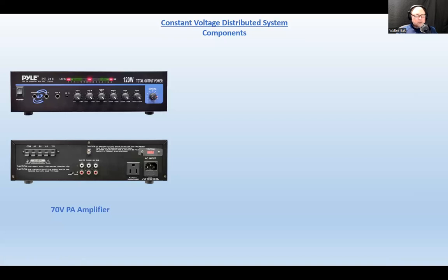And that would be annoying. So in order to remedy that, there would be a dry contact or relay input here to activate that input. So when the telephone system function is selected to do an audio page, then the audio output of the phone system gets activated and the relay closes on the phone system, and it closes the contacts on that amplifier to activate that input for that time of the audio page. And then when somebody hangs up and the page is done, then the relay releases and the input becomes inactive.